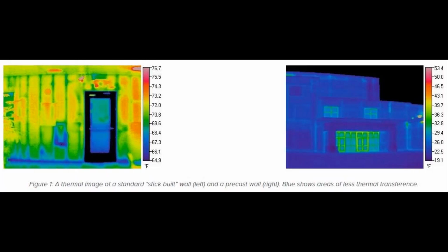Another is thermal efficiency. Edge to edge, top to bottom, rigid insulation can be used within a relatively thin wall, providing a high effective R value. The thermal mass of the concrete provides an added benefit by slowing heat transmission through the wall, flattening out the temperature swings. It can be used in conjunction with the building's thermal performance, which can actually double using precast wall elements. This in turn can reduce the size of HVAC units needed.